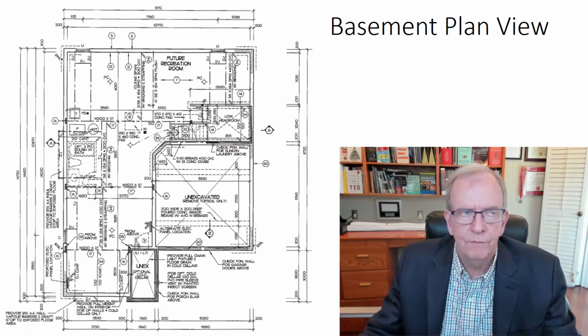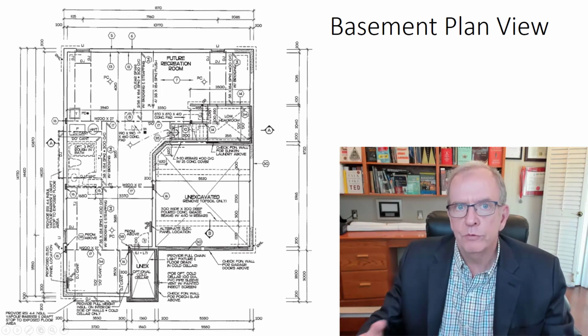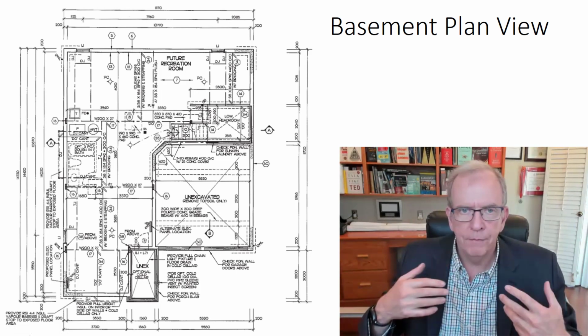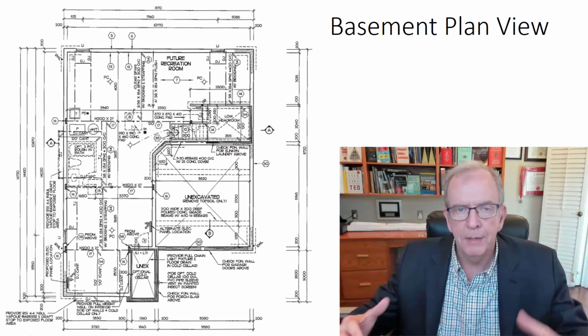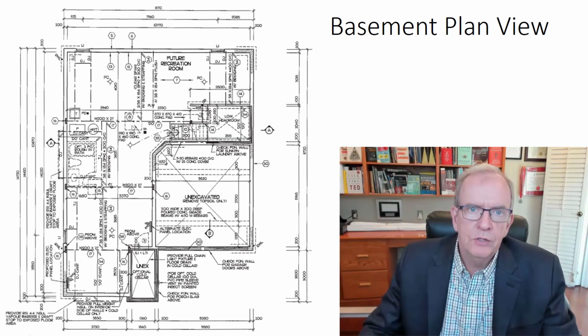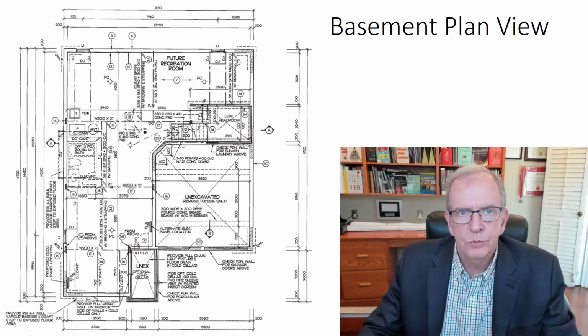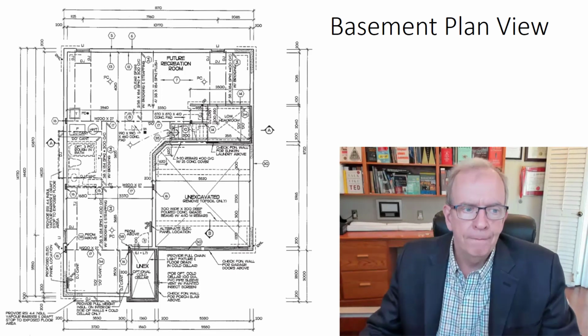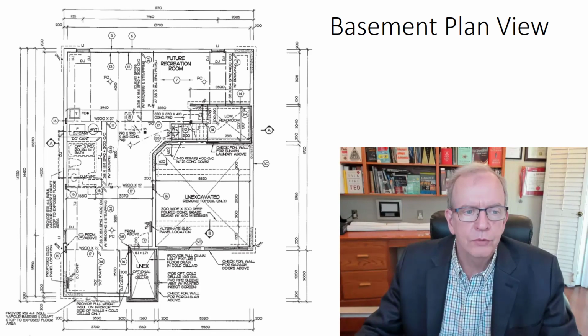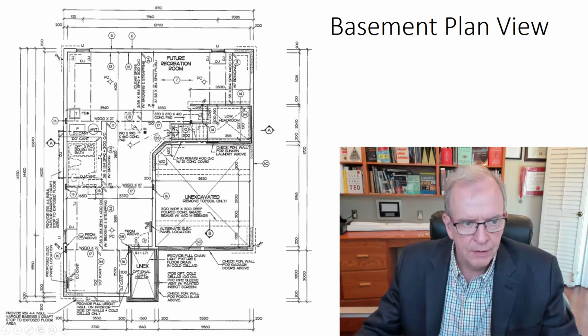Snow loads, in this particular case, because it has roof trusses, it's not really supporting the weight of the roof, only the outside walls are, but live loads can be. People, furniture that can be moved around, the weight of snow when it builds up and then it melts. And dead loads are the weight of the structure itself, the walls, the drywall, the roof shingles, all of those things that are attached and part of the building. It has to be able to carry both of those loads, and so it's designed for that.